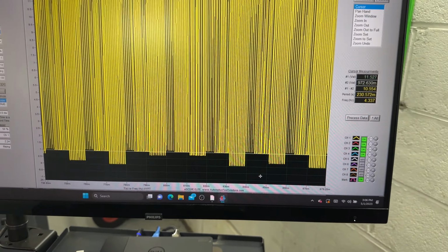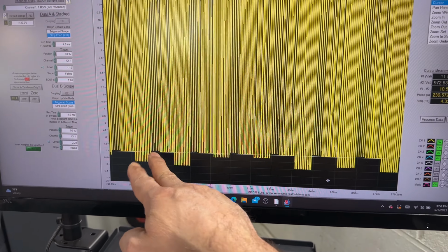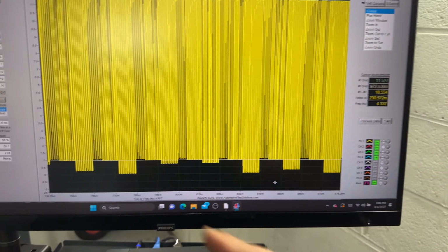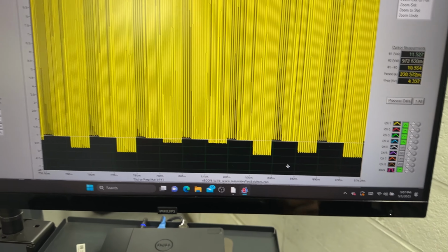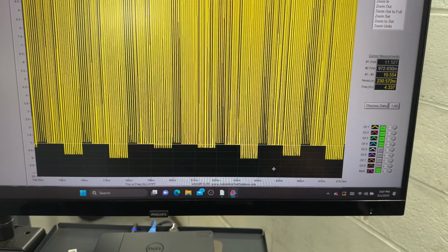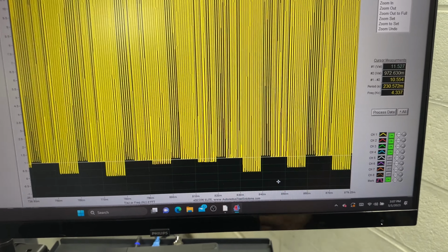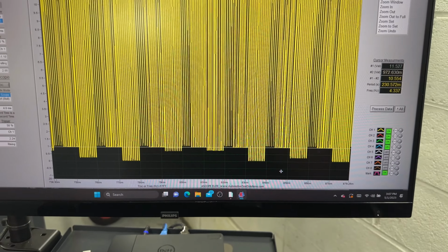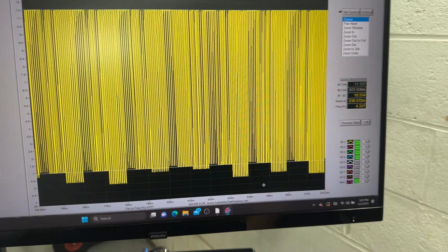So definitely we have problems. This is where modules 1, 2, 3, 4 are connected, let's say, and then we repeat 1, 2, 3, 4 modules. This is like the responses of the modules, but the amplitude is incorrect. This should be around 12.3 to 12 and a half, and depending on the battery voltage, even up to 13 volts. So this is too low. So we definitely have a shorted module. Let's call all these components modules because they're smart sensors.